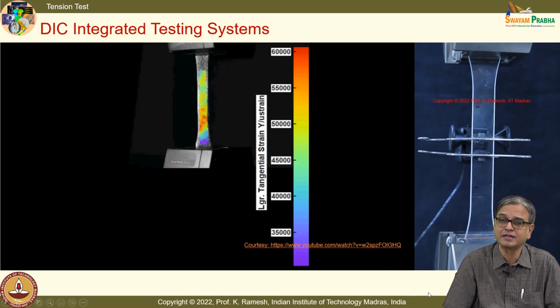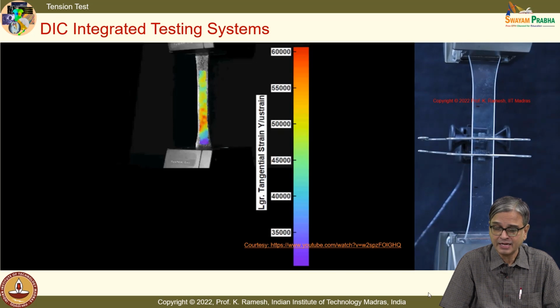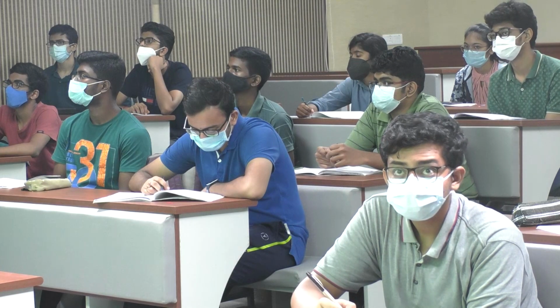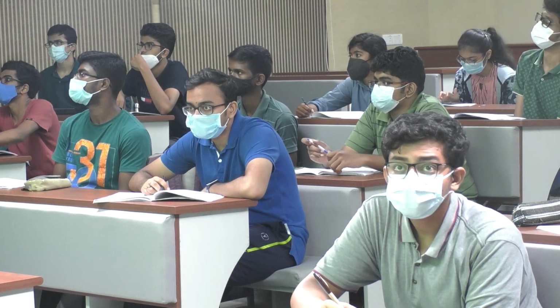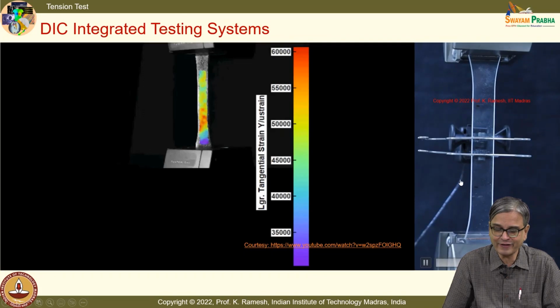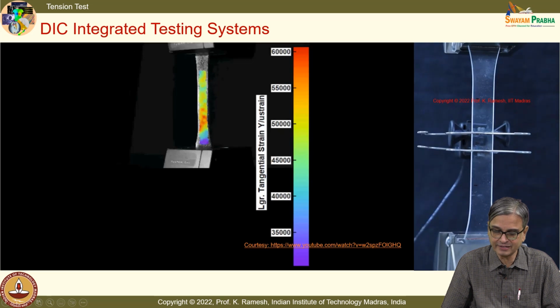See, if I have a photoelastic material that we have used as epoxy, epoxy fails in a brittle fashion. It depends on the hardener that I impose. And you can see the failure; how do you anticipate the failure? It is a brittle material. Let us see, you will also see the failure towards the end. So, you have a fairly good idea even before we take up the theories of failure that a brittle material fails in a particular fashion and a ductile material fails in another fashion.